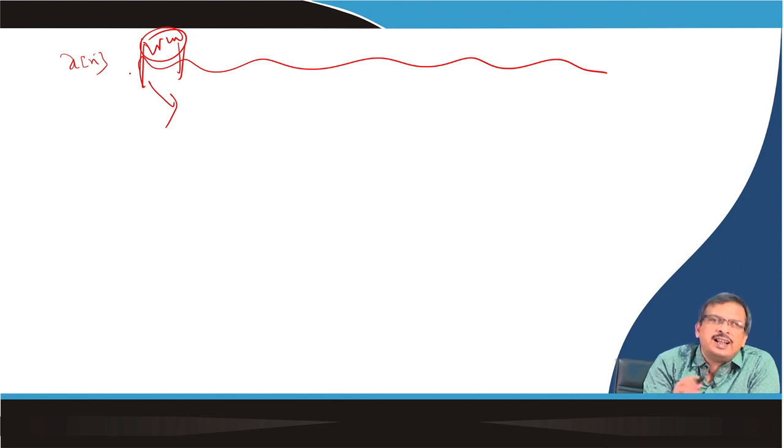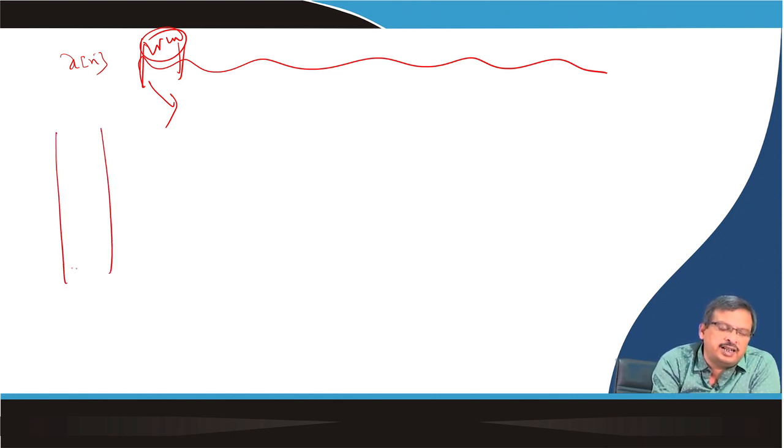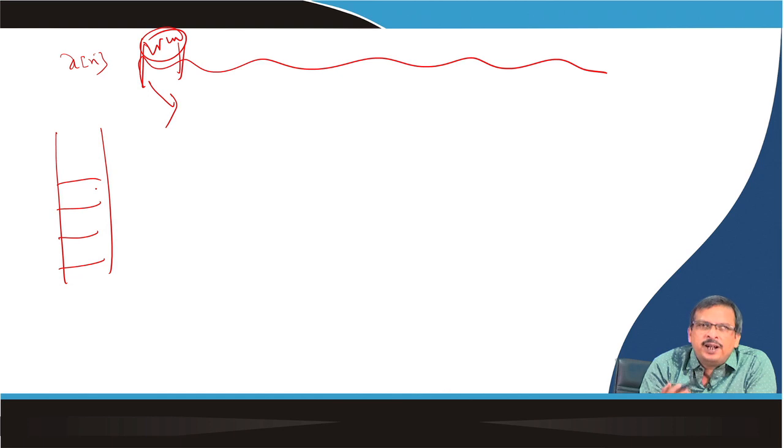Okay. So, when I write, there are different window functions, as you know: Blackman window, Hamming window, Hanning window, rectangular window, and I have described the effect of each window. With some windows the main lobe is very wide and the side lobe leakage is less, but in the rectangular window the main lobe width is less, but the side lobe leakage is very high. So, you know that I will not get the original signal spectra only; the original signal will be convolved with the frequency response of the window spectra.